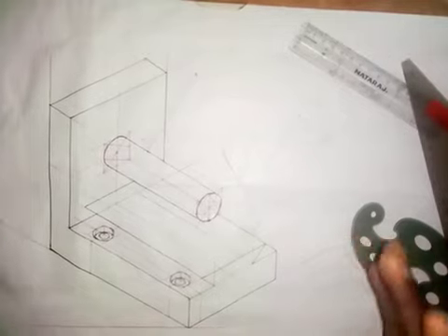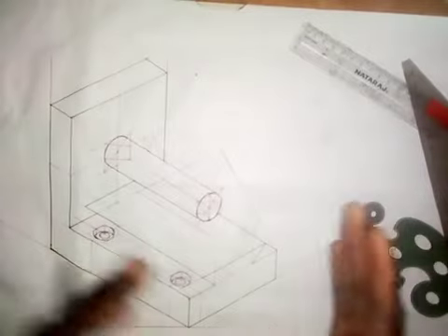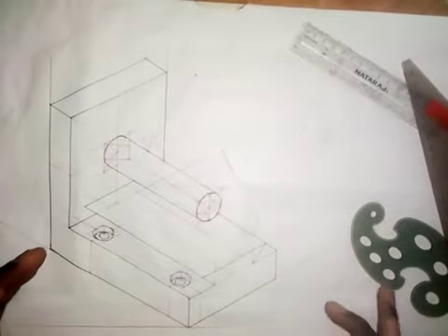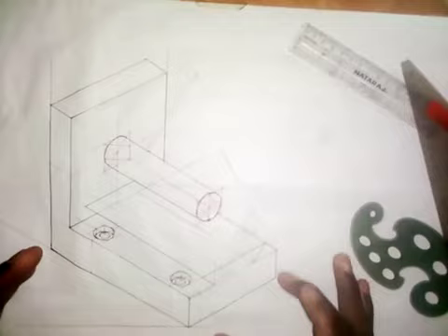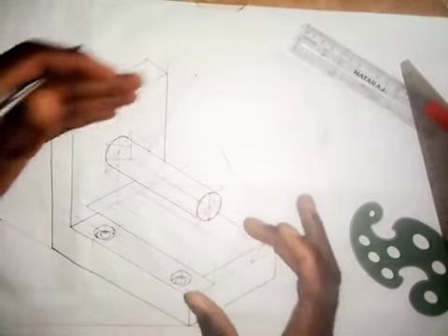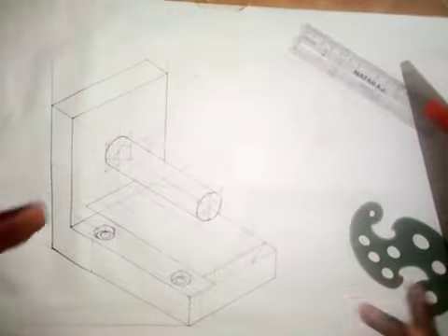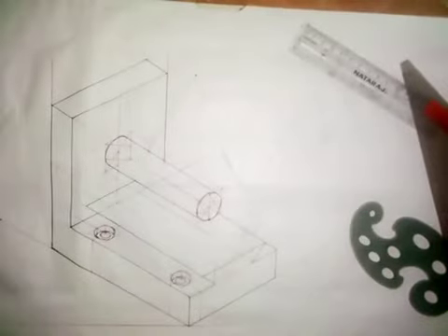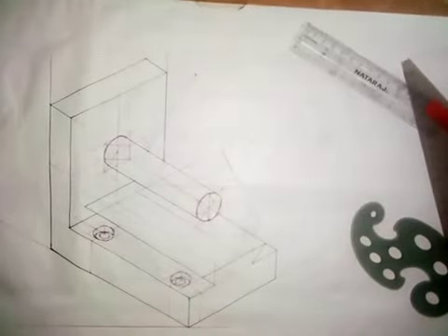So we are going to put part A and part B together. As I said, part A is coming on this, so it will enter this, and then face C will rest on this face D. This is face D to rest here, and then as we are told, part A is sliding on this part B. So all you need to do is to practice. I've done many works on isometric projection, conversion of orthographic views to isometric view. So I've done a lot of work on that. So just practice and you master it.